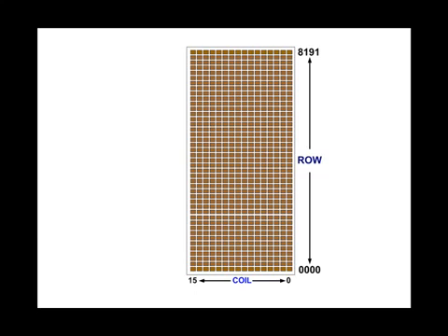You could say that if you want to query or question a particular relay coil to see if it's in the on state, you would use a normally open contact. If you want to query or question a particular coil to see if it's in the off state, you would use a normally closed contact. The use of these contacts to check the state of the relays is the basis for all relay logic.